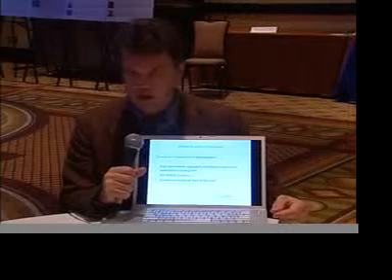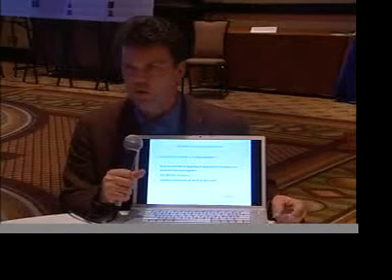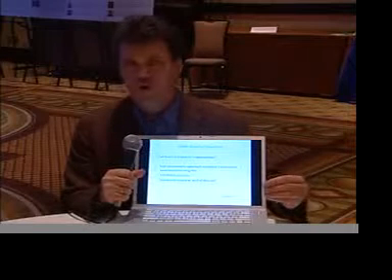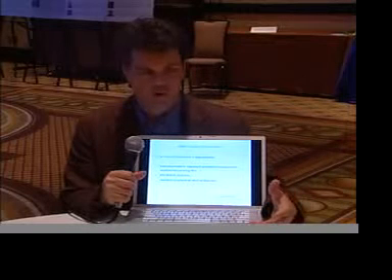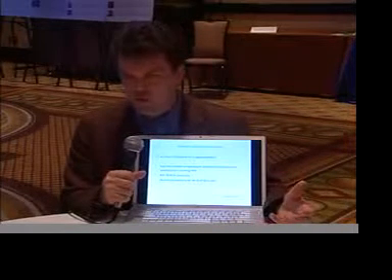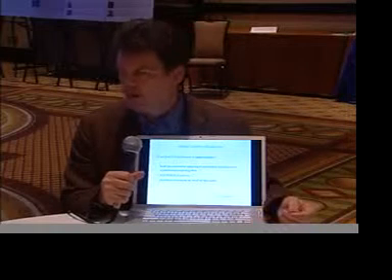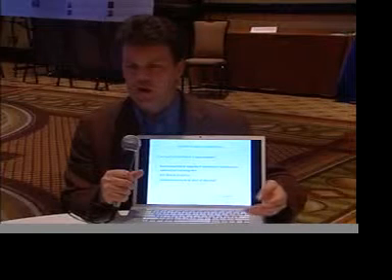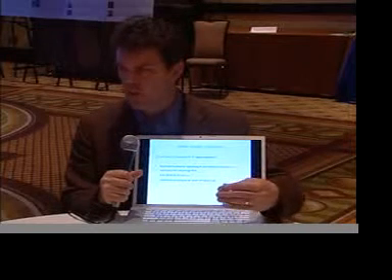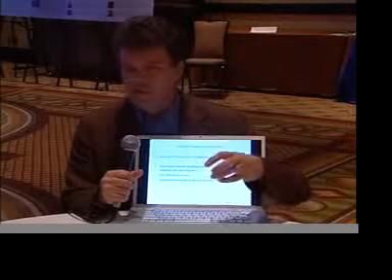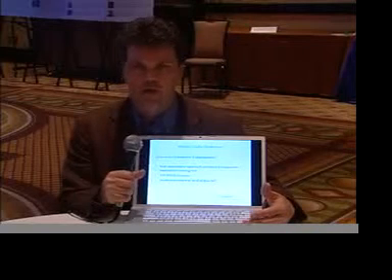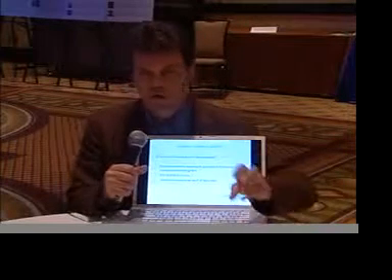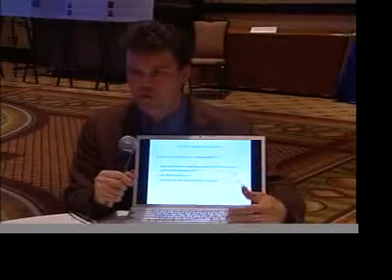There's a fairly detailed risk assessment approach that we go through on every project that we do for determining how much treatment we need. And the way it manifests itself might be, like I say, if we're doing rainwater harvesting for subsurface, we might do no treatment at all as long as you've got a mulch barrier, and that can be demonstrated as appropriate through this risk assessment public health methodology that's been established by people like the World Health Organization, using some fairly detailed risk and exposure calculations to support what we do.